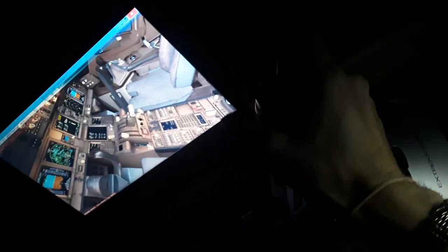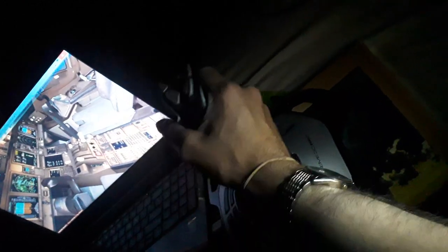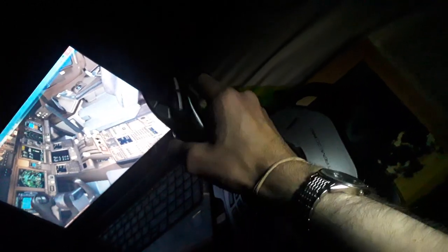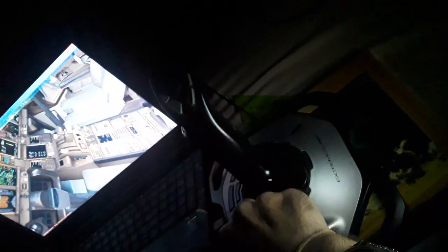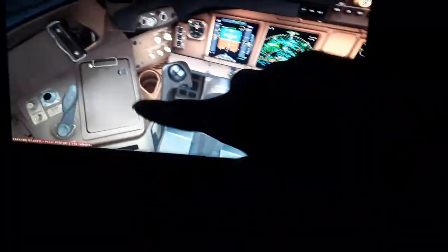We have also the other trim. So this is generally what you do: climb with the horizontal tail, the elevator, climb and descend, pitch up and pitch down. Also the ailerons, bank roll left and bank roll right, you can see both sides are moving together. So climb, turns, and also the rudder pedals, very important, left and right turns, and the engine thrust lever function. You also have over here the tiller for the nose steering on the ground.